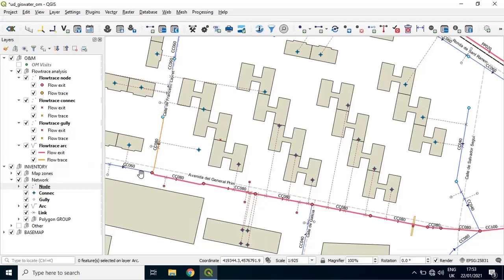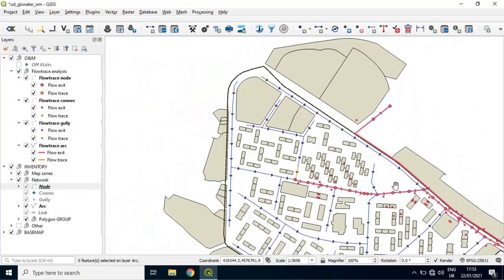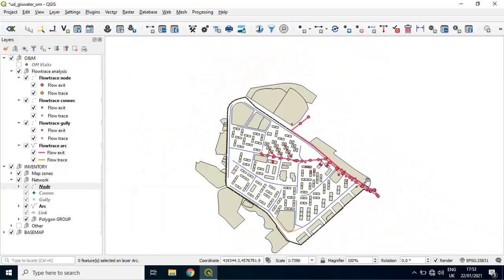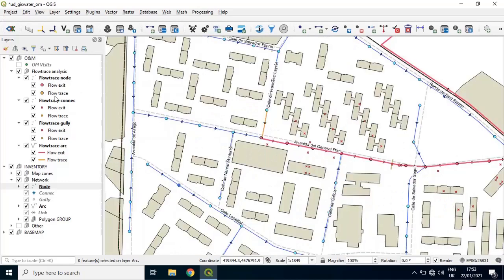of the network. One of the goals of this tool is to help find errors in the network, since the elements upstream or downstream must have a coherence of heights so that water flows through the conduits. If the top elevation of a manhole that should be upstream is smaller than its predecessor, the tool will stop, and it will not be selected.